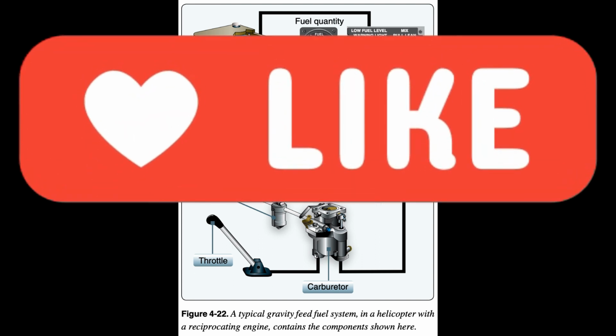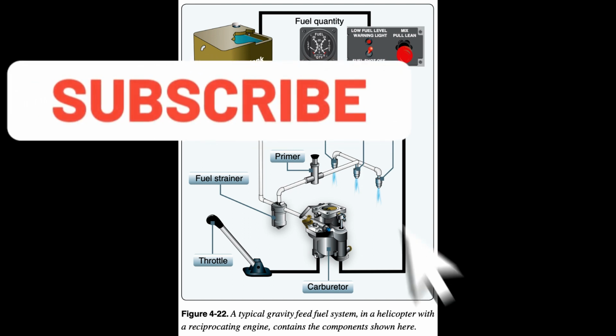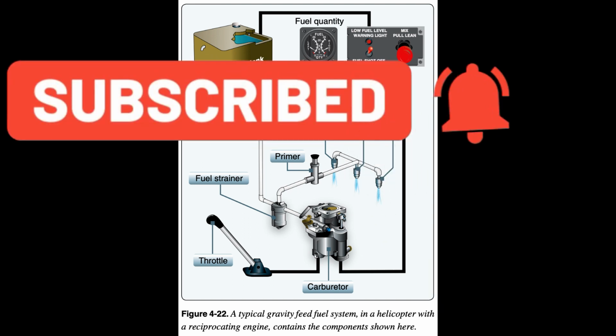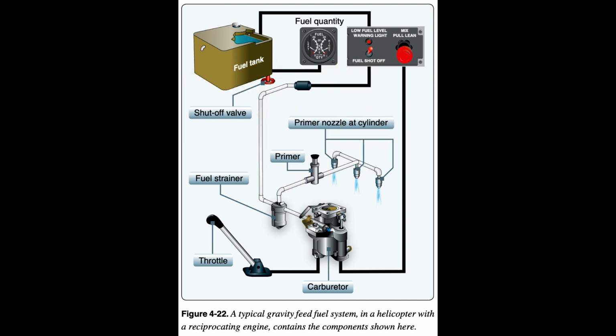Regardless of the device, the reciprocating engine and the turbine engine both use the ignition and combustion of the fuel/air mix to provide the source of their power. Engine fuel control systems utilize several components to meter the proper amount of fuel necessary to produce the required amount of power. The fuel control system, in concert with the air induction components, combines the proper amount of fuel and air to be ignited in the combustion chamber. Refer to the Pilot's Handbook of Aeronautical Knowledge for a detailed explanation and illustration.